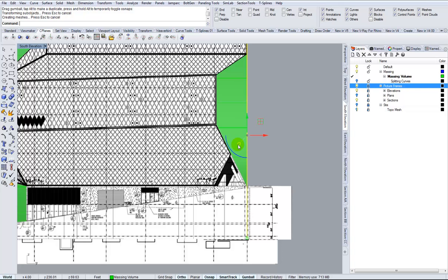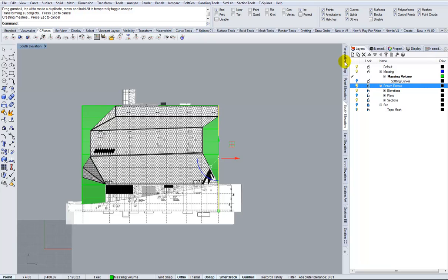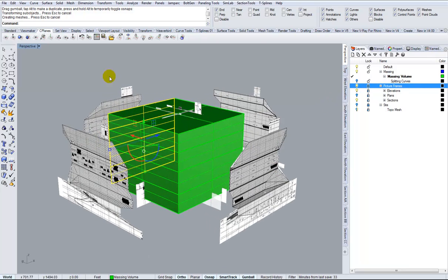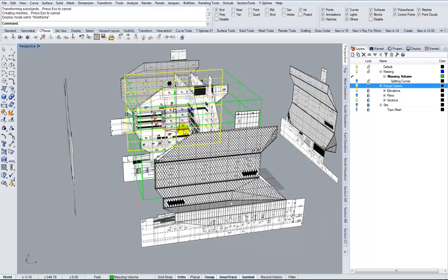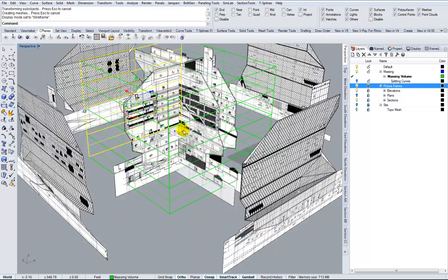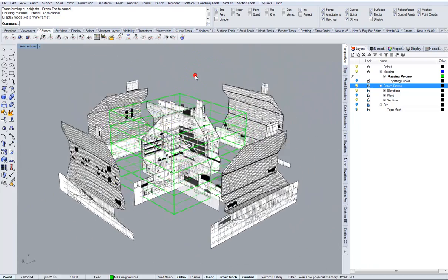On my gumball options here, if you click the white bunny tail there, we've got snappy dragging on, so I can use my snaps when I drag to the objects. So it's a little bit tighter, it's a little bit closer to what we want for the volume. Not there yet, obviously. I'm going to do an incremental save now.